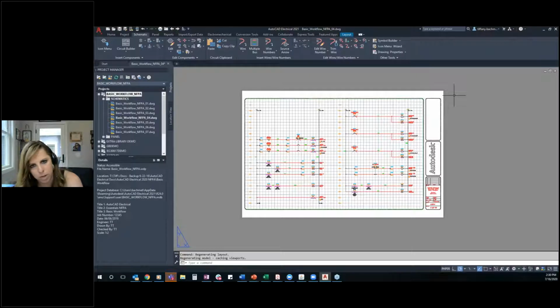It's exactly how it's going to print on my plotter at a B-size format, so that's 11 by 17. Now I have viewports, so anybody who knows standard model space and paper space working formats, you put a viewport into your title block, and that viewport allows you to access anything in model space and then scale it. So if you take a look at my particular viewport that I just grabbed, there we go. You can see down at the very bottom of my screen, if you can barely see it, it's at a 1:2 ratio. So I'm actually using scale.